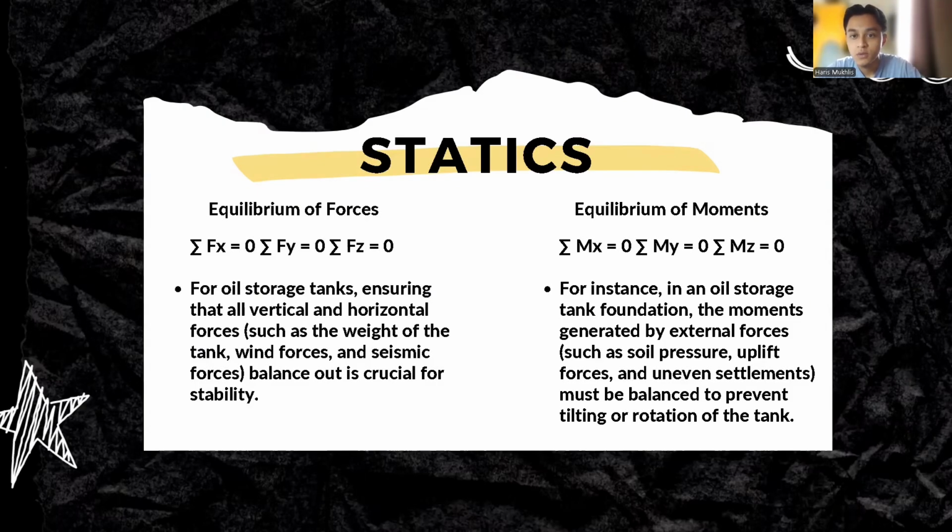And the next one is equilibrium of moments, which is sum of moment x, sum of moment y, and sum of moment z equals 0. For instance, in an oil storage tank foundation, the moments generated by external forces, such as soil pressure, uplift forces, and uneven settlement, must be balanced to prevent tilting or rotation of the tanks.